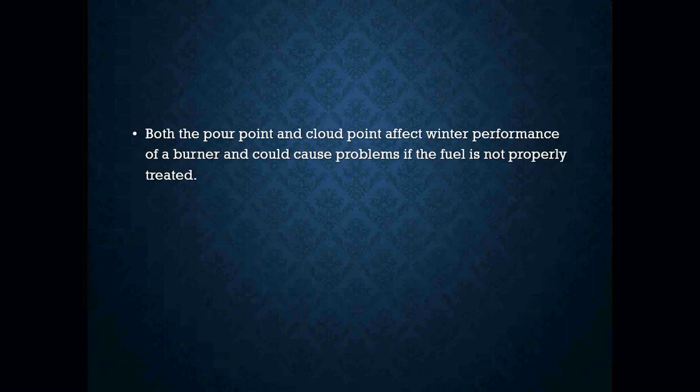Okay, you've got to first figure out what the problem is. Then you have to make sure that the fuel sample being tested represents the fuel being treated. With the additive, will the additive be used once, or is it going to be a continuous type of treatment that is going to be required? Does the additive perform more than one function?